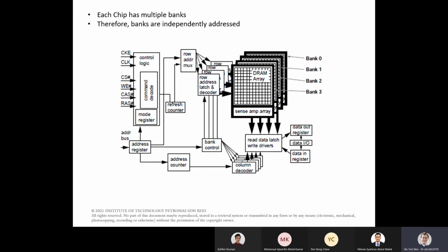So the way to parallelize it is, I have my runner go to post office 1 and say, get me from box number 5. Then the fellow goes to the back, there are many boxes there, 6 million boxes, right? I have to go to which row, which column. It takes a while to walk there because it's very, very large. Then while he's doing that, doing his row access and pulling it out, my runner goes to post office 2 and says, now I want box 16 from post office 2, right? So the postal worker in post office 2 will start to go into their big post office vault. Wow, that's 6 million again. I go to the row and all that.